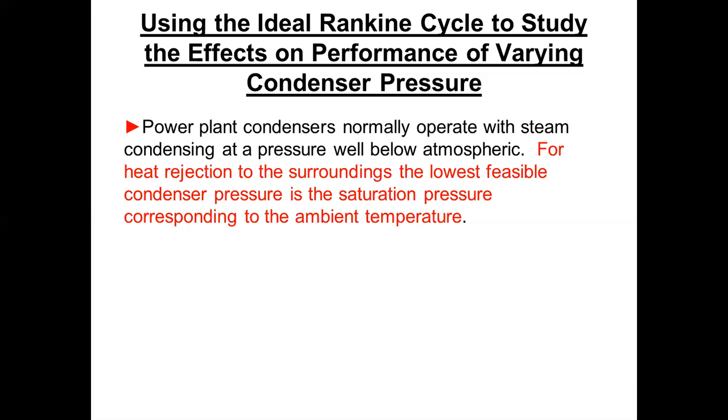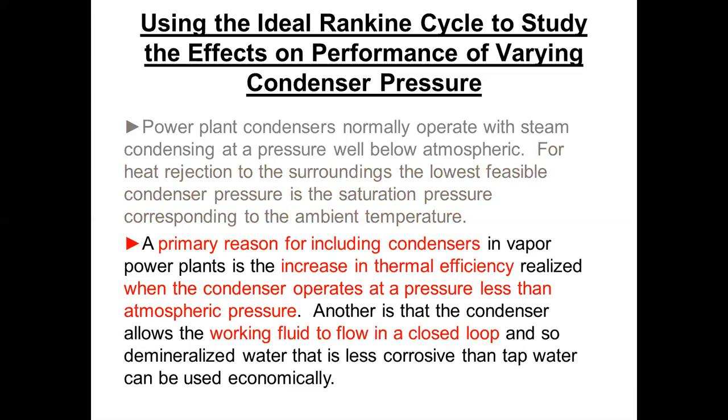So if the lake water is 50 or 60, you're going to see that condensing temperature is between 105 and 110, maybe 120. And you need that finite delta T in order to be able to buy a small enough heat exchanger for your condenser that you can afford to buy it.